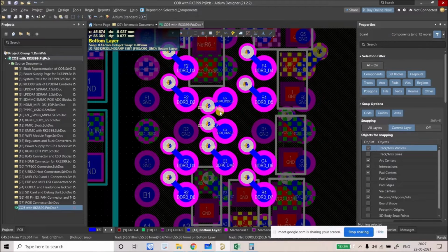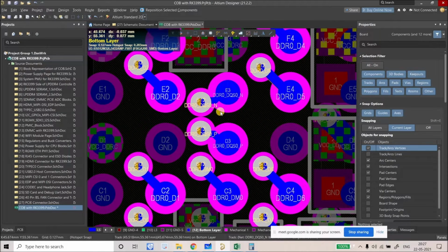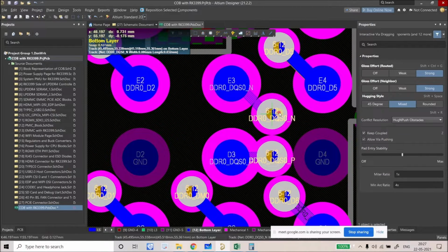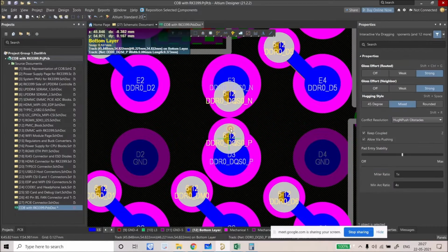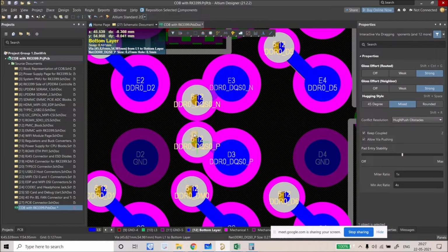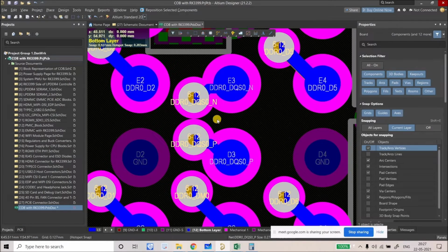Hello. Yeah, Ashish. Can you please put the wire template on any one of the pins, beside the pin, and 180 degree rotated to the other pin? Okay, you are saying one here and one at this side. Exactly. But what is the point of that? I mean, we can do that because here we are not following the differential coupling, right? Here we are not following what should be the clearance between differential tracks, right? So we can do that. That is also a way.